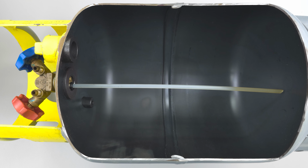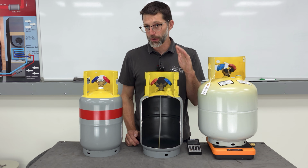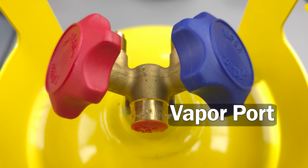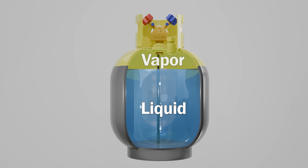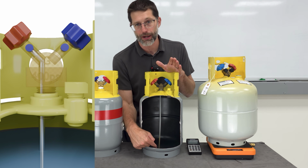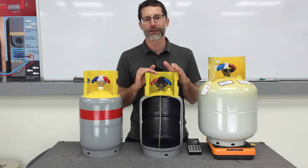There's a dip tube on this side, and that's connected to this red handle right here. The blue handle is just attached right to the top. What you really want to pay attention to is less the colors and more the word. So this says vapor on it. The vapor is attached to the top of the tank, because as you fill this recovery bottle, it's going to have more and more liquid on the inside, and your vapor will be up at the top. This dip tube on the liquid side goes all the way down to almost the very bottom. The issue is we have some recovery bottles out there that have the wrong colors on the handles, so you really need to be careful with that.